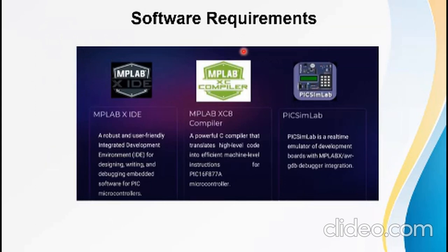So here are the software displayed on the screen which I used in this project. First is MPLAB X IDE, a robust and user-friendly integrated development environment, IDE, for designing, writing, and debugging embedded software for PIC microcontrollers. Next is the MPLAB XC8 compiler, a powerful C compiler that translates high-level code into efficient machine language for the PIC16F877A microcontroller. PICsimLab is a real-time emulator of a development board with MPLAB X debugger integrated.